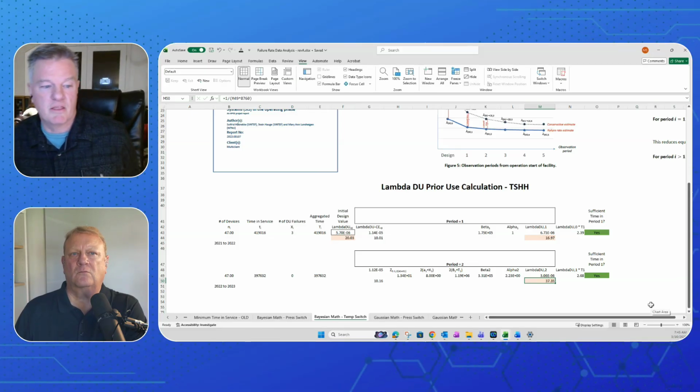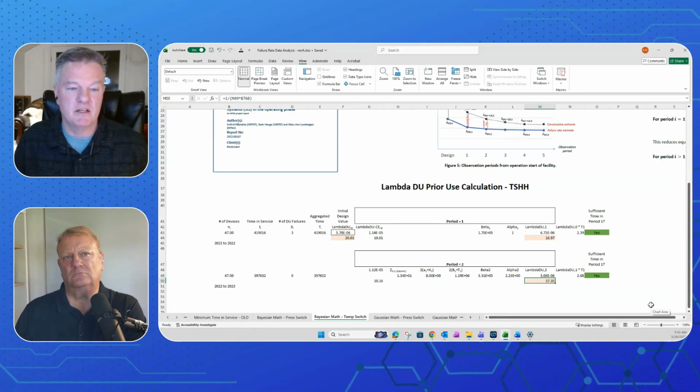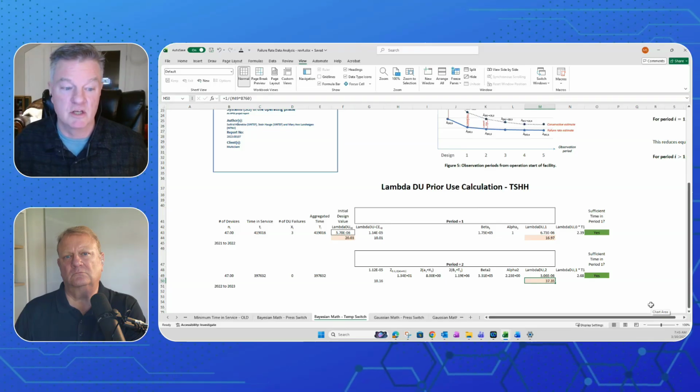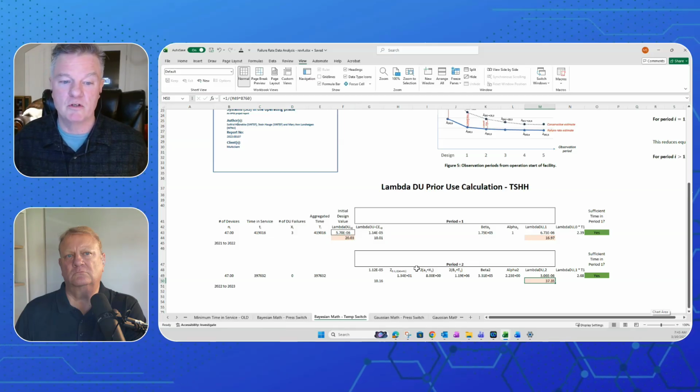As part of this project, they had not really ever done a LOPA. They had a new risk matrix. So we went ahead and did a risk matrix, did a LOPA worst case scenario, assigned targets to this. And even though we had a crappier pressure switch number with a 1 out of 2 vote to trip between the 2 devices, I could still extend testing.